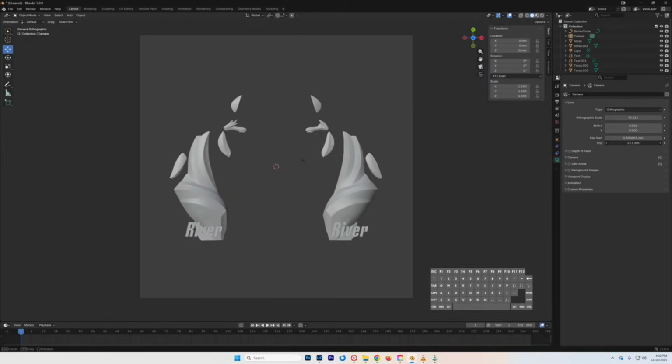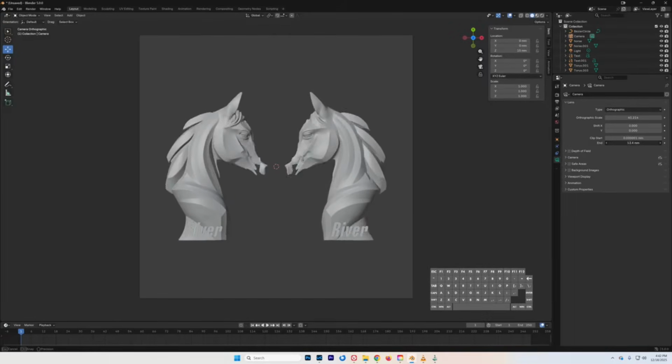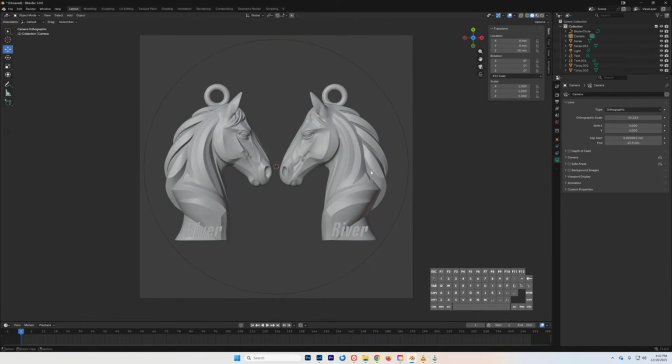So everything's going to come back into view, and you keep sliding slowly until we see that circle come back. That one right there, not the ring, but the circle that is our boundary, because we put that at 0. And now everything is in view of the camera, and this will make sure that you get a very good depth map.